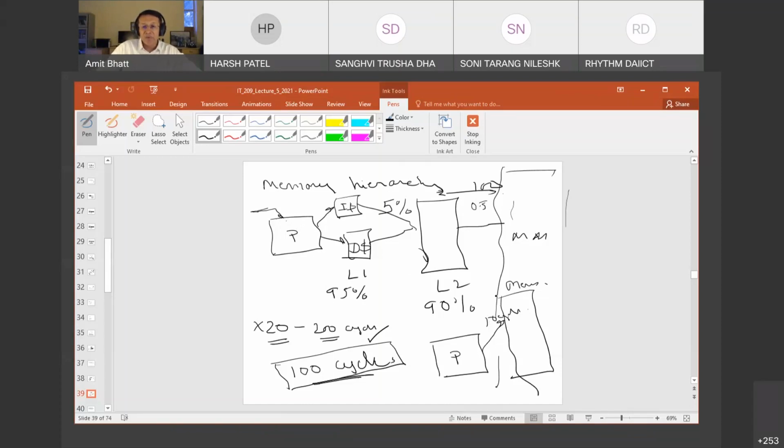So the guarantee would be dependent on two parts. First is, how long would the processor take to wake up and start executing? That is called latency. And then, how long it would take to get the whole program and finish the execution. Based on that, you can say, this is my hard deadline: from the signal coming to the processor to the end of the execution of a real-time program, it would take 100 cycles.